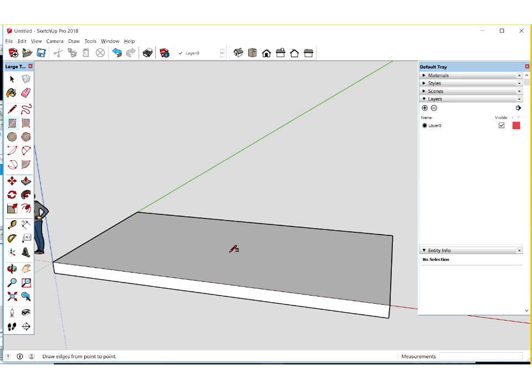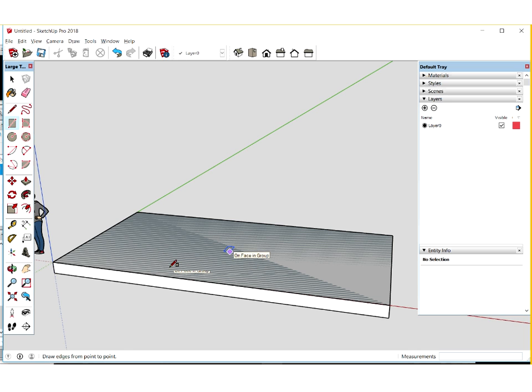Now we've got a box for our slab that's grouped together, and I've just created another rectangle on top of that, and you'll see that funny shimmer effect on the face. If you ever see that with your materials, it means you've got 2 surfaces that are on the same plane that are competing for real estate there. So when you've got that, you know that you need to end up deleting one of them, otherwise your materials won't display properly. So we can use the offset tool, even if you want to work along with this, for everyone who is working along, we can do these walls together.